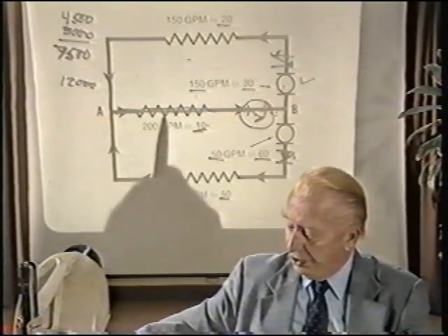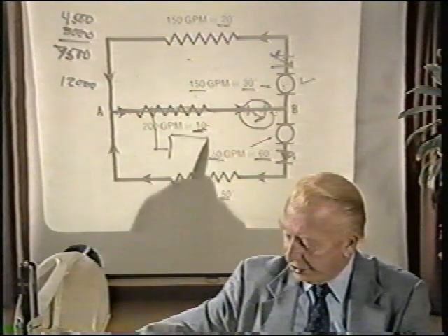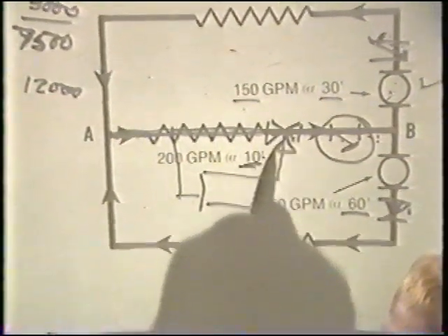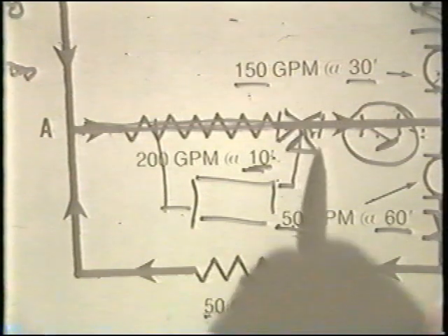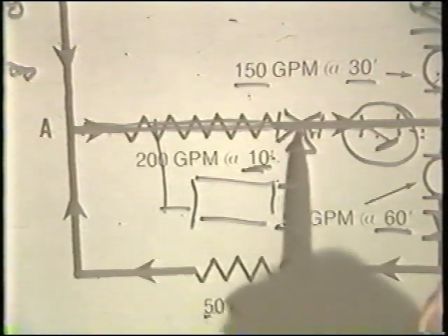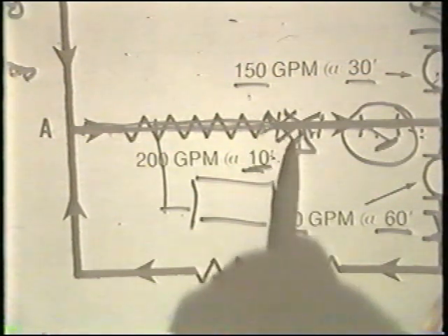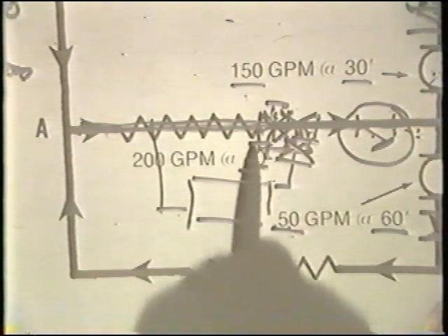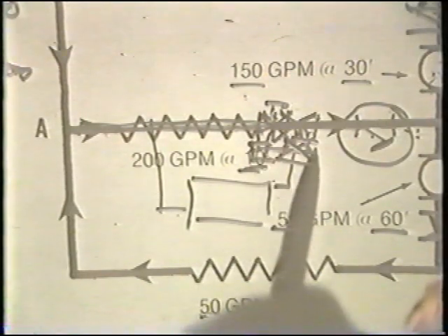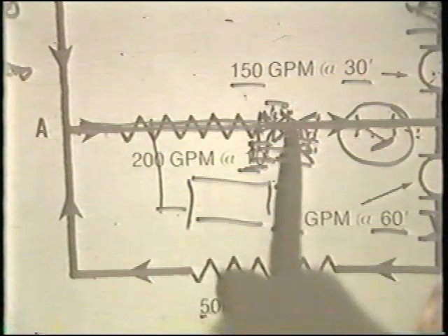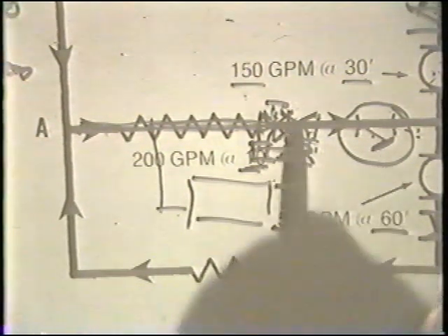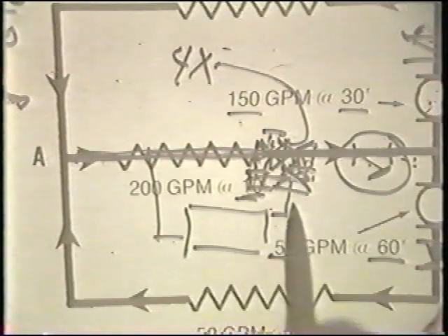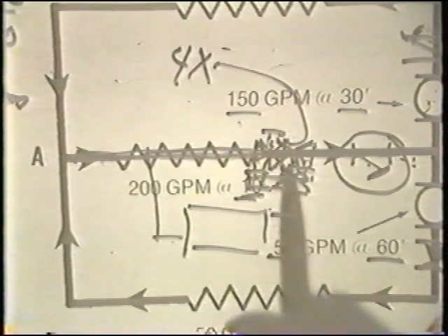Another problem that occurs is that if this system included a boiler, for example, with a resetting 3-way control valve for reset of water temperature, and if that reset were accomplished by 2 butterflies, as illustrated here, the butterfly control valves will, under a 50% flow condition through the reset of that valve, establish 4 times the head loss that would occur if flow occurred only through one valve with the other valve closed.